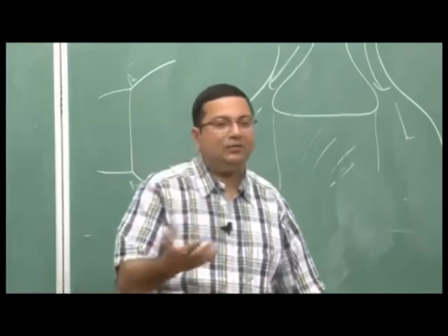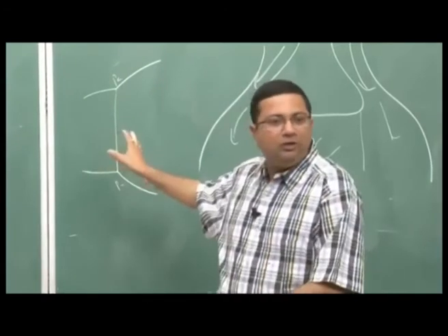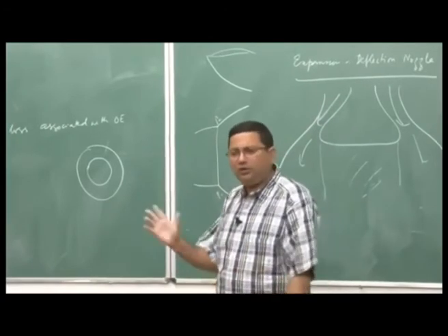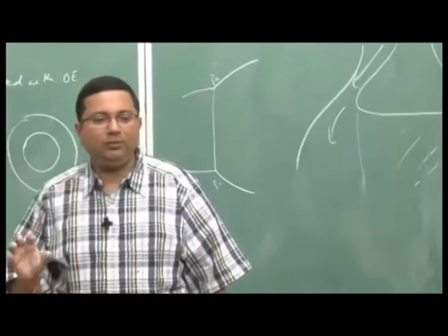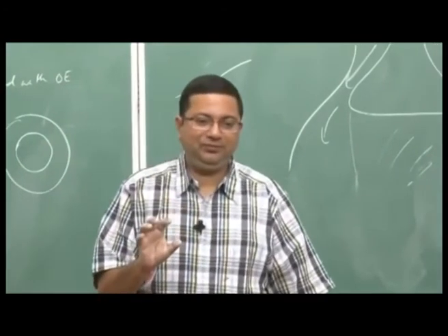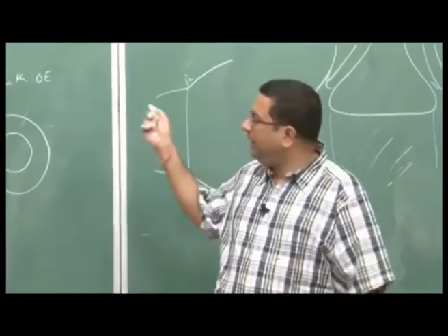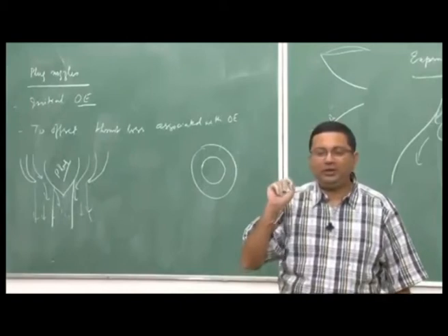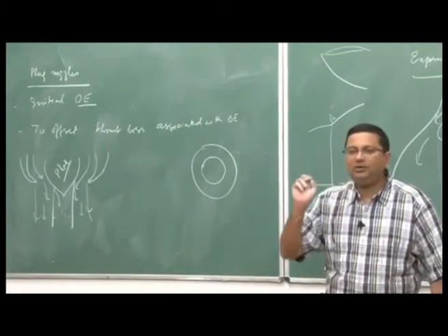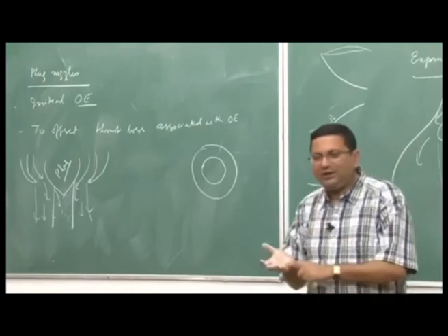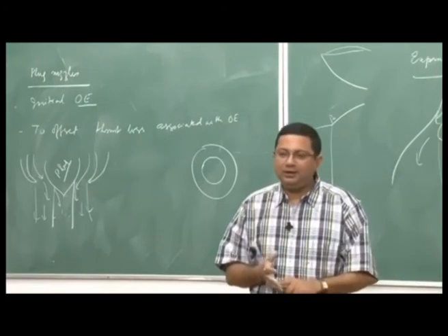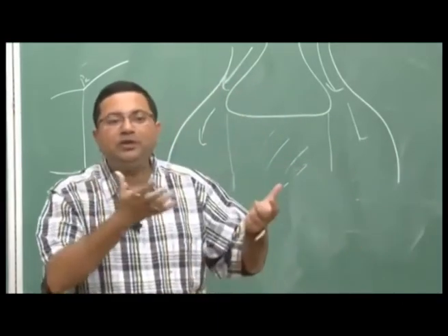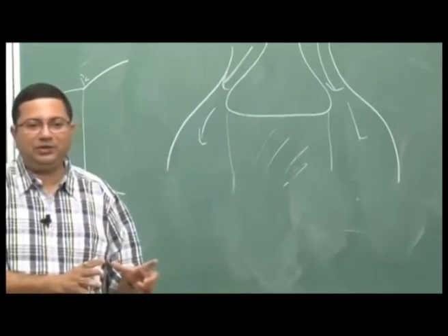Now, chamber pressure, as I have said, comes from the pump and all, we want to maximize it, but there is a limit, we do not want to go beyond that. So, next thing we talk about is the temperature. Another parameter that appeared again and again in all our derivations was gamma, the ratio of specific heats, that depends on the composition. So, the temperature as well as the value of gamma and R, both of them essentially are the output from the chemical reaction or combustion that is occurring inside our combustor.